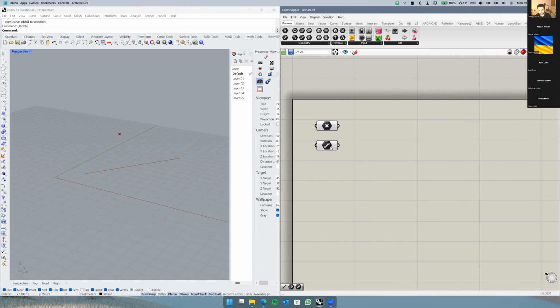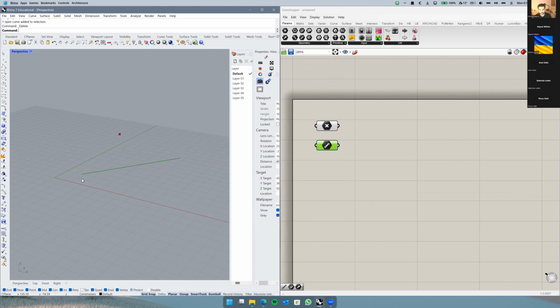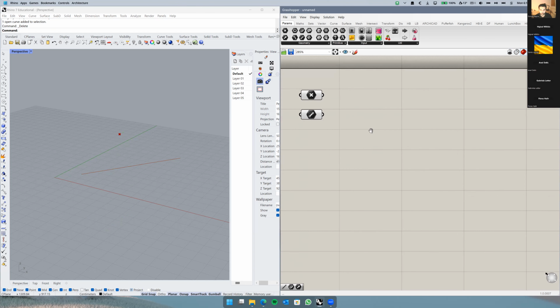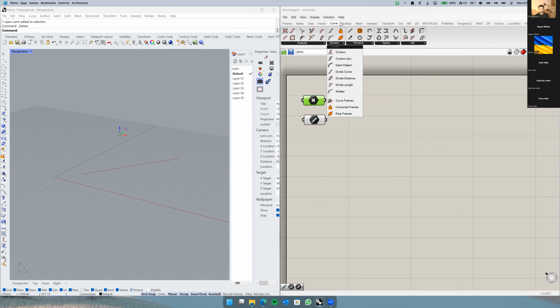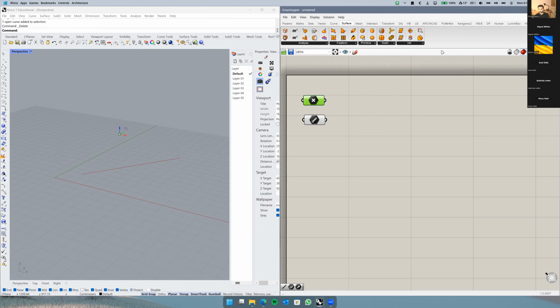Now, right now we saw examples of how to define a point or a line by ourselves, just drawing, the original way, I would say. But what if I want to create a point from certain coordinates, for example? First of all, either you can go to the menu, and if you know where it is, you can choose what you want. In many cases, I don't know where they are, so I just use this method instead. I double click on the canvas and it gives me an enter a search keyword box. So here I can type in what I want.